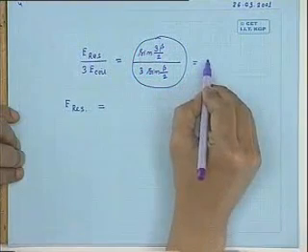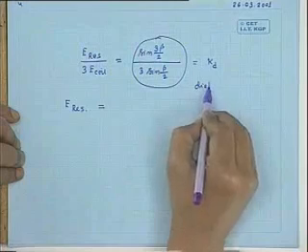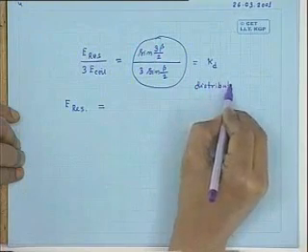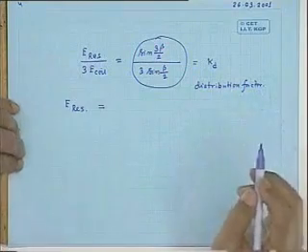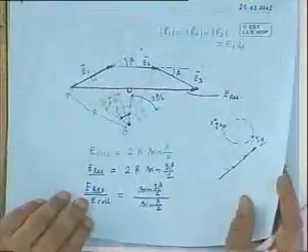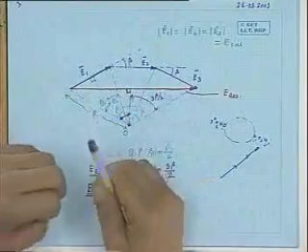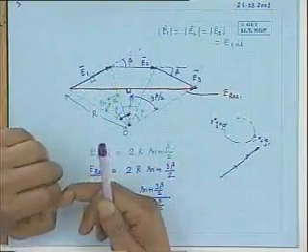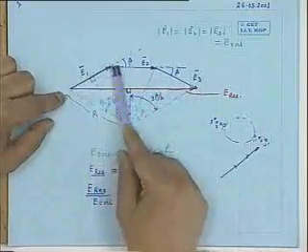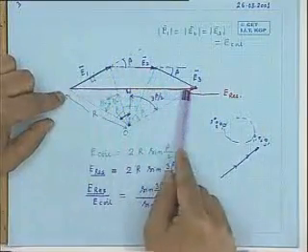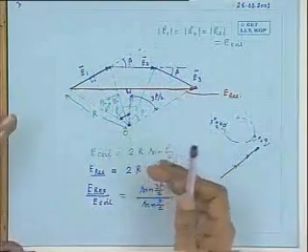Let this factor, I will tell you why it is called so, be called the distribution factor. Obviously, because of distribution of the coils, the E resultant obtained will be less than when the coils were not distributed. This length is obviously less than the sum of these three sides.